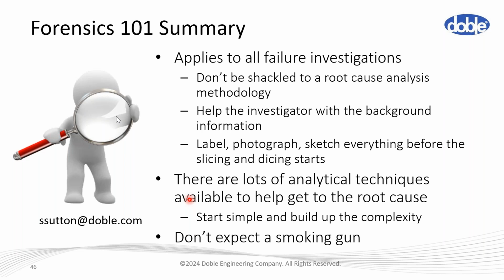This case study is an interesting one because, okay, you've got the wires there, they're going to act as stress enhancement, they're going to lead to discharge. That's a pretty good smoking gun. But it's not the important thing in this investigation because of all the issues with the air voids, the PD, and all the other joints, and the tearing of the silicone rubber. So it's very hard to avoid jumping to conclusions.